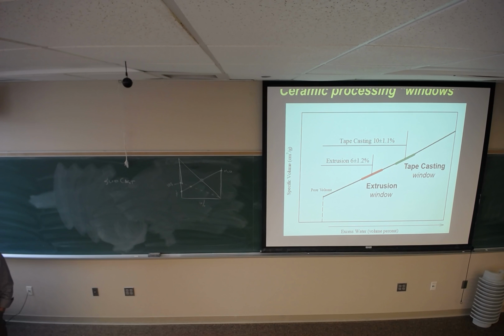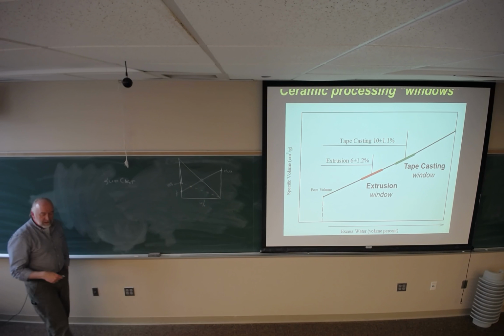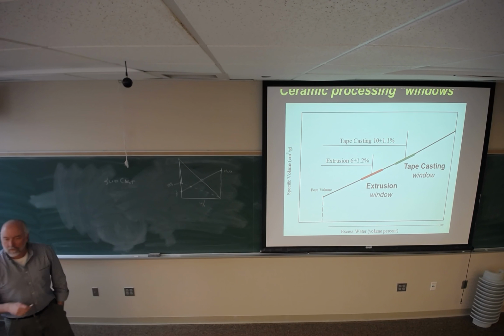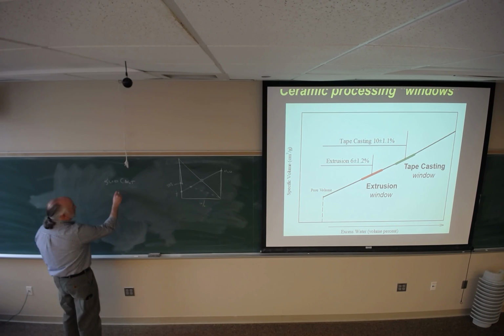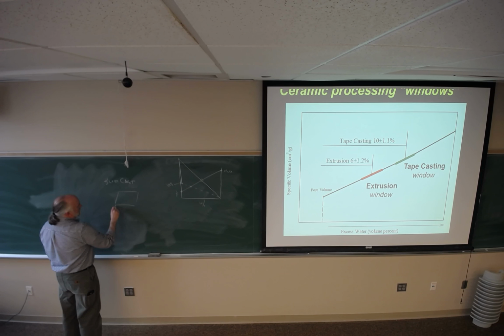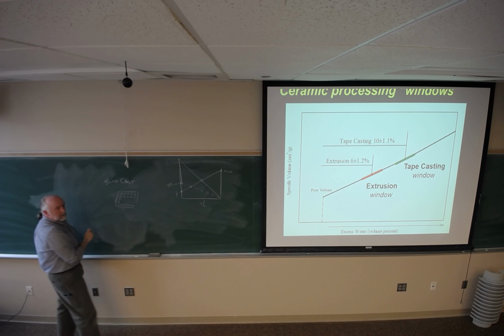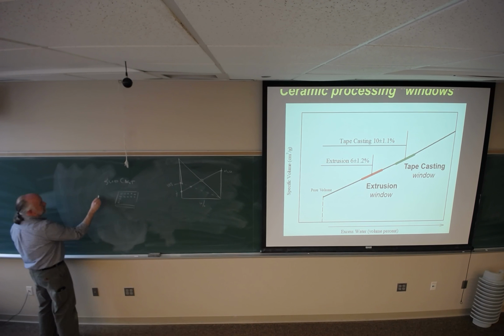You want it to be flocculated or dispersed? All right, so let's make it dispersed. Make up a dispersed suspension, and you cast a pellet. We have a bunch of molds. They typically look like this. They're Lexan or plexiglass, and they have essentially 25 holes in them. I can draw all these on here, but I don't need to. And then you get out of that a little pellet like this.